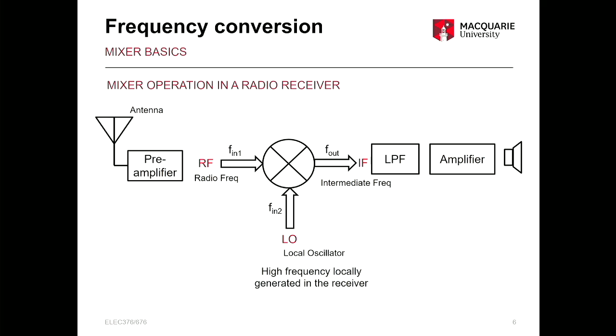And once you amplify it, then you give it to a mixer. There are different stages of amplification in there, and changes to correct for the non-linearities and things. But it's too complicated. Now you give that to the mixer RF, and you locally generate another frequency, and then you get the information contained in that, which is in the intermediate frequency. For radio, it's 455 kilohertz, which is like a standard for a radio. So you change your information from that RF frequency to the IF frequency. Now you can use low speed electronics to amplify it and hear the voice.